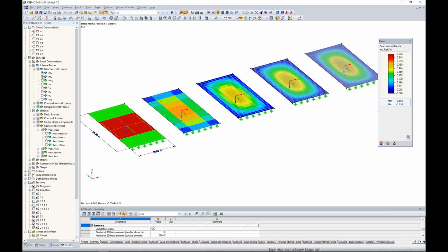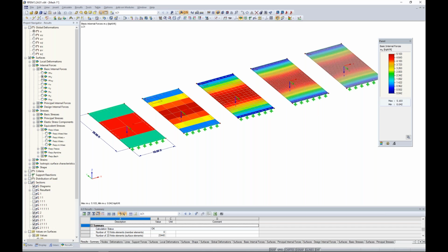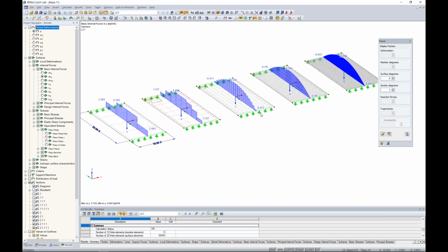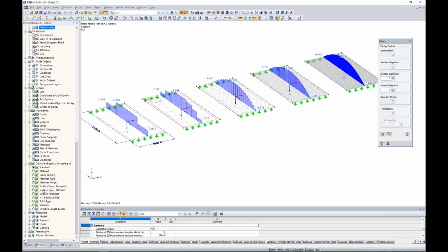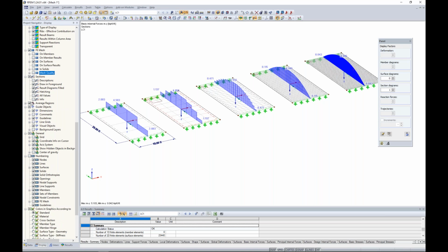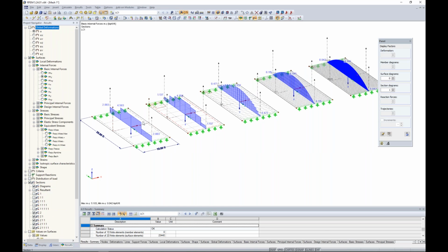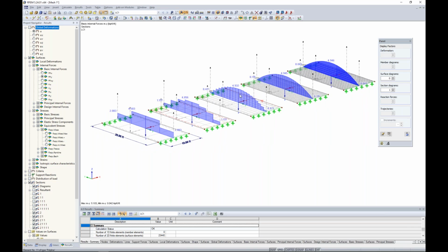Now we can compare section cuts as well. I'll turn on these sections and turn off my ISO band so this is a little easier for you to see. I made this cut right down the center of these surfaces, and under my display tab, let me also turn on how those cuts were made. I'm currently looking at the MY force, again along the length, and you can see how the diagram of this section cut changes. We're definitely getting a much more realistic view as we move into the finer meshes.